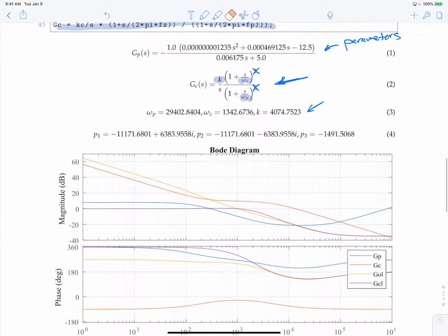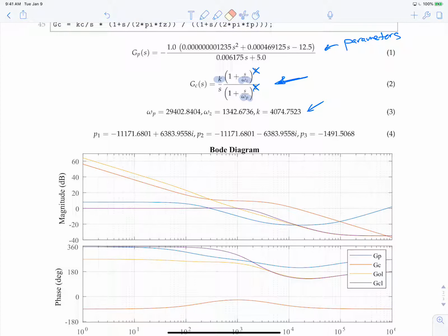So let's go ahead and take our Bode plots and take a look at them in terms of the plant transfer function, etc. GP is our plant. You can see we have a fixed gain. We have our pole, and then we have our two zeros, which is interesting here because what happens with the boost converter in current mode control is the gain actually starts going back up this way, which is really bad because generally at high frequency you want to roll the gain off at least at minus 20 dB per decade so that you don't run into any stability issues.